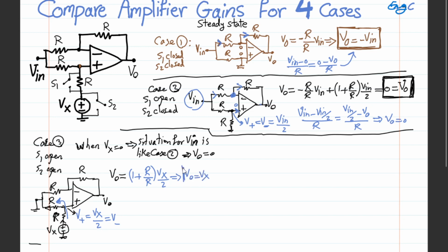That is the conclusion in terms of what we have for output voltage as a function of input voltages. Vx is only contributing here. You can also write KCL if you want to prove this, but it is the same as what we did before. So the voltage drop across R on top should be the same as the voltage drop across R at the bottom, because they are effectively in parallel since they have the same voltages on the two terminals.